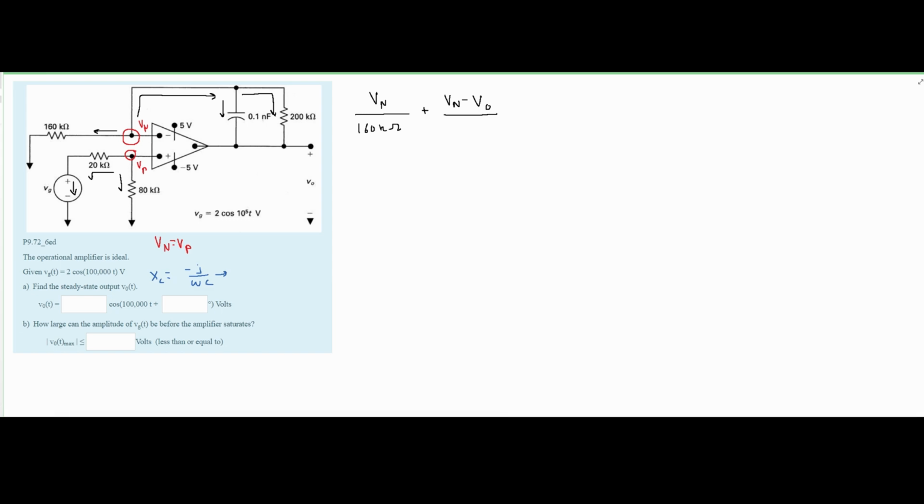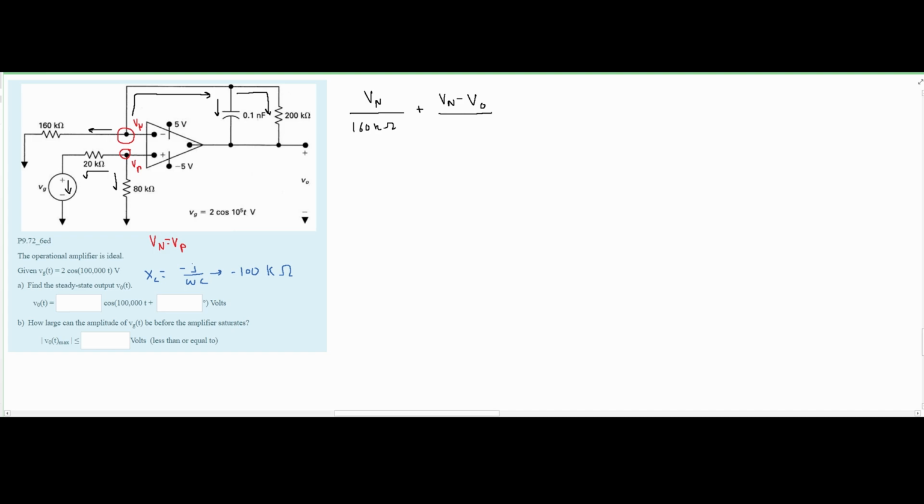And if we do this, we are going to get -100,000. We can also write this instead as -100 times 10 to the cubed. Or we can say that this is 100k for kilo, and since this is an impedance, it's going to be in ohms. And lastly, we are going to have our j in here. We cannot forget our j, otherwise it's going to mess up the entire problem. So this is going to be over negative j, 100 times the kilo ohms as units.